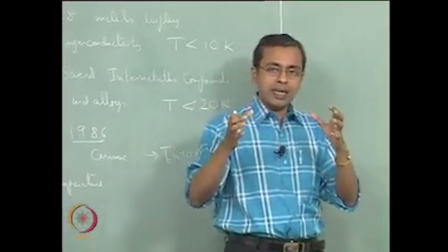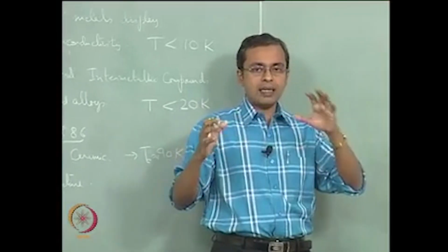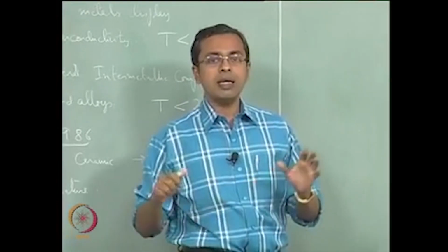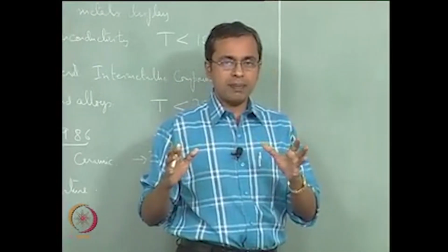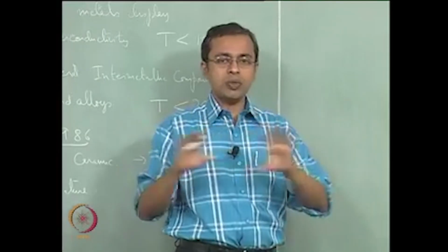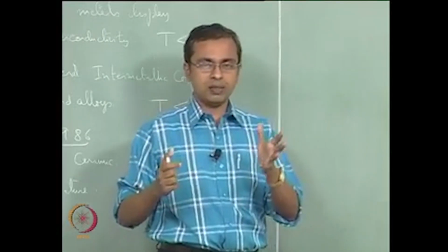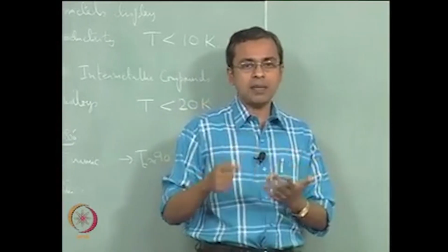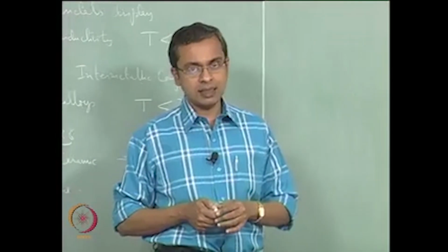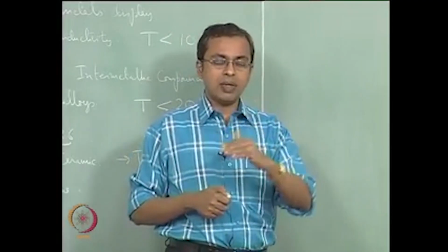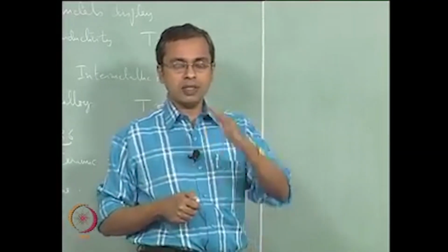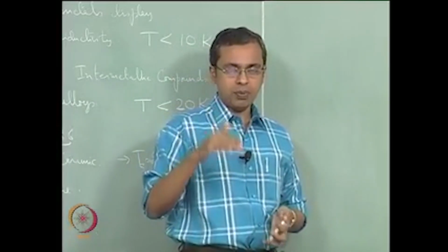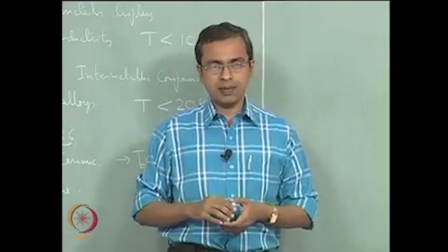Also similarly, you can take a superconductor and place it in the presence of an externally applied magnetic field, and in the presence of an externally applied magnetic field, it will continue to remain superconducting. You keep increasing the field. So we spoke of magnetic fields. We basically had said that the externally applied field is a field that we would designate as H. So you can increase H, in amperes per meter. So you keep increasing H, then you will reach a certain value of magnetic field imposed on that material when suddenly the superconductivity breaks down.